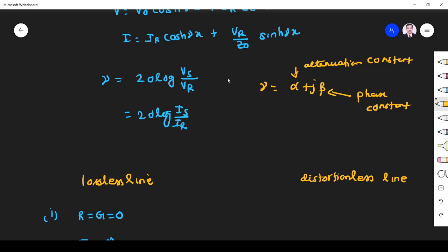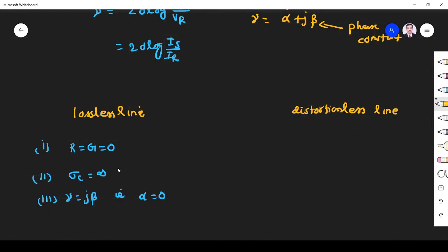Okay, so this is another important equation you must remember. So what happens here is, for a lossless line, attenuation is 0. That's why it is called lossless. See, that is very important. Right? For a lossless line, it has no loss. No loss means attenuation is 0. If attenuation is 0, then the propagation constant is purely a function of phase constant. Okay, fine.